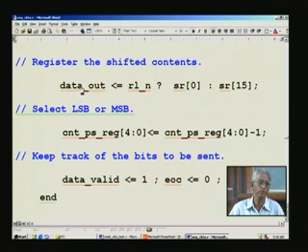And that is being sent to data out. Mind you, data out is only a single bit output as such. On the other hand, if it were left shift, that is, this will be deasserted, logic 0 low, and then in this case we have to send the MSB out. That is what is being done here, and having done this, you have to decrement the counter that we had, which keeps track of the number of bits sent.